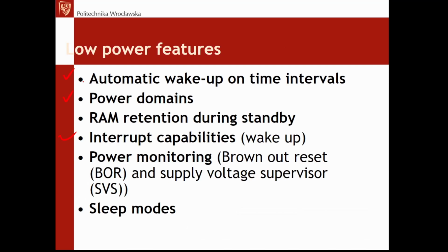Sometimes the groups are sharing clocking, and it means that we can switch off the whole group and then switch it back again, which saves time and energy, because we don't need to switch every peripheral separately. We can switch them back together at the same time, and we can control the clocking or power supply of those peripherals as a group, not one by one.